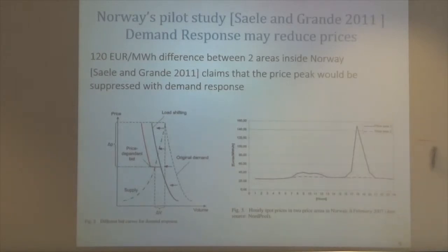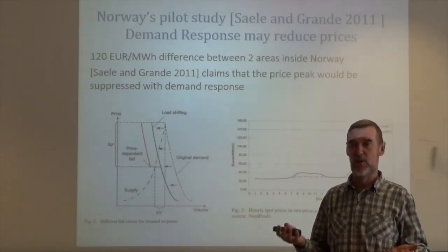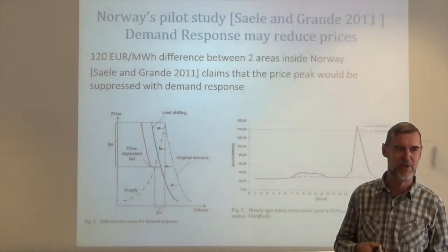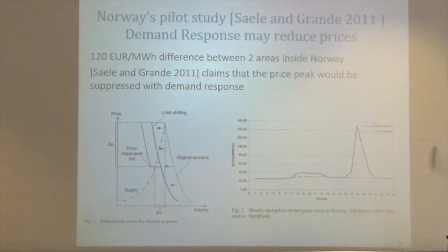This could happen, for example, when there are highly congested lines and there's overproduction somewhere. If there's overproduction of solar PVs and you lose a high voltage corridor, then what do you do with that? An intelligent thing would be to curtail the PVs, but if you don't have the means to curtail, you may put the prices negative to force other people who are able to respond to price to absorb that energy.